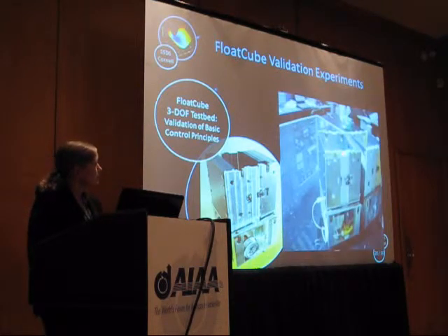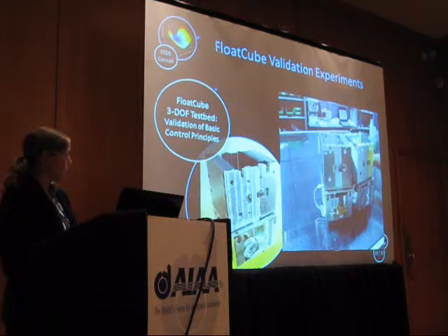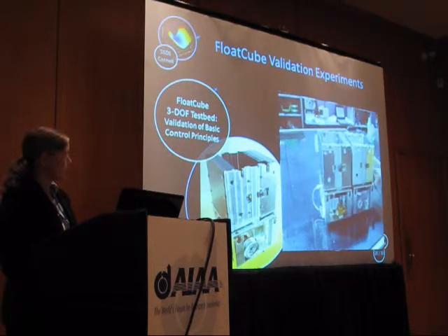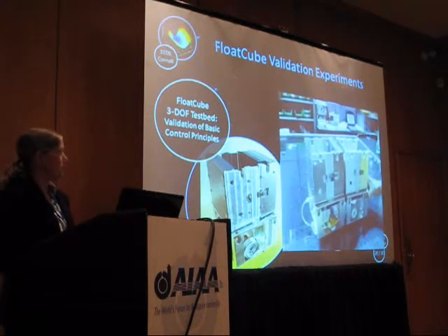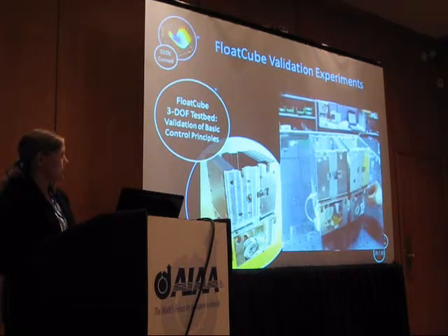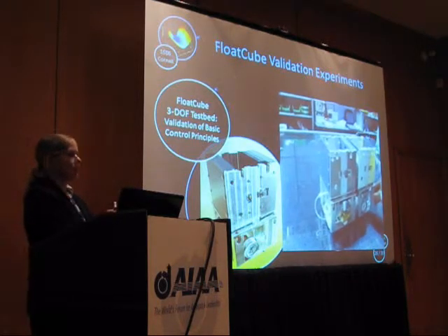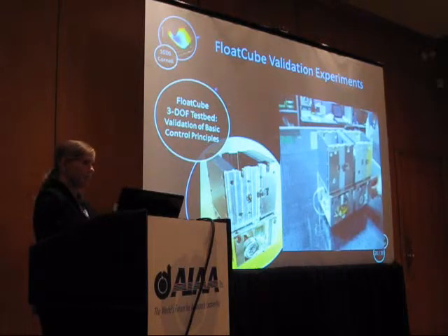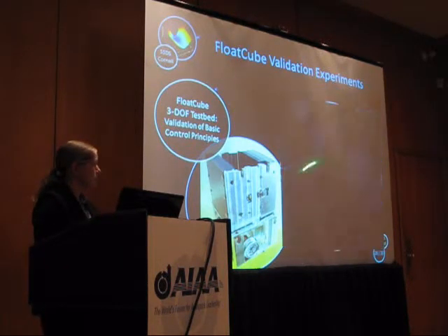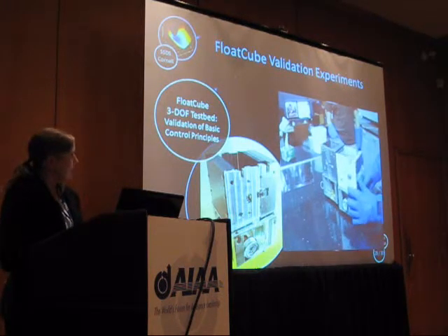So what we are seeing here is a Flux-Pinned docking interface. You've got a Flux-Pinned system where you've got YBCO on one side and your magnets on the other, and they're staying at the position that we cooled it at, which is about 1 centimeter. Right here, you can see that you can drag the system, and the attraction well is strong enough to bring all of them together. You can repel it by pushing one module, and they both try to seek that same equilibrium, and they stay together. You can see it right there, as it drags around.